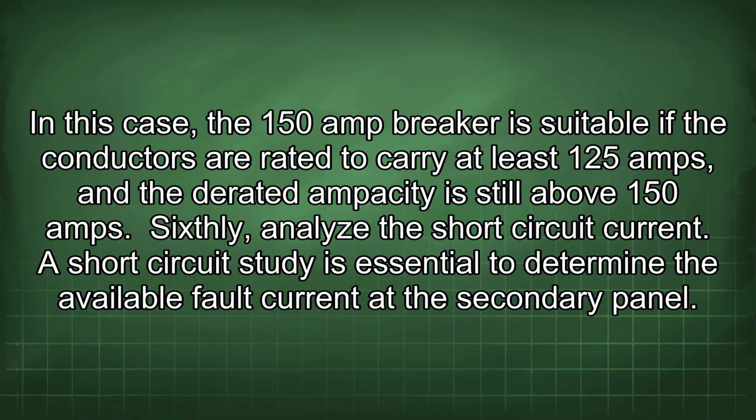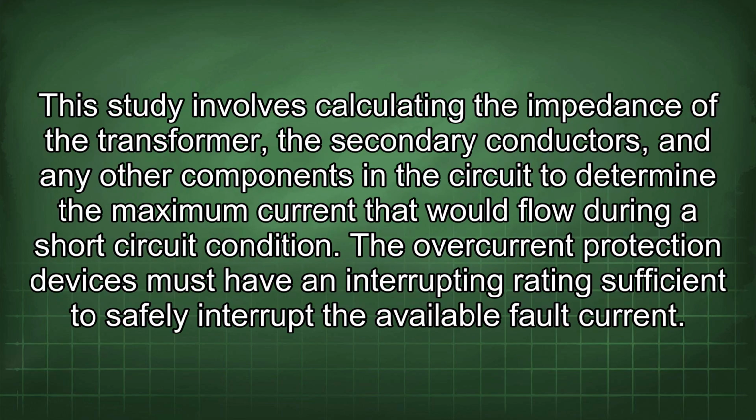Sixthly, analyze the short circuit current. A short circuit study is essential to determine the available fault current at the secondary panel. This study involves calculating the impedance of the transformer, the secondary conductors, and any other components in the circuit to determine the maximum current that would flow during a short circuit condition.